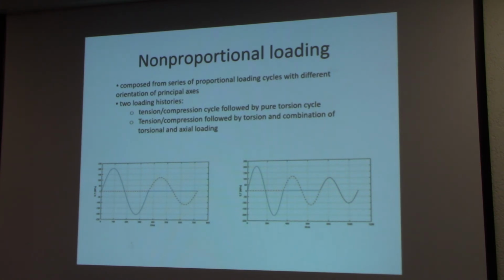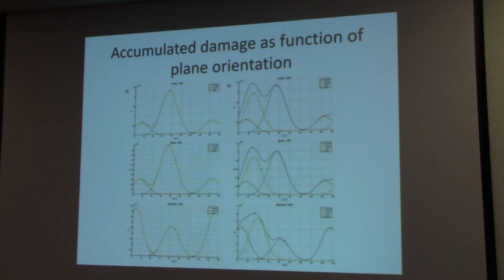Okay. The amplitude of these loadings was chosen so that the maximal so-called von Mises amplitude is the same for all three of them. Okay, so we will take the maximal normal stress amplitude and maximal shear stress amplitude, and calculate the von Mises stress from them. It will be the same for all the three, because the problem is to design the loading sequence to have similar damaging potential for one loading cycle. Okay. So here are the results for the calculation and what it does.